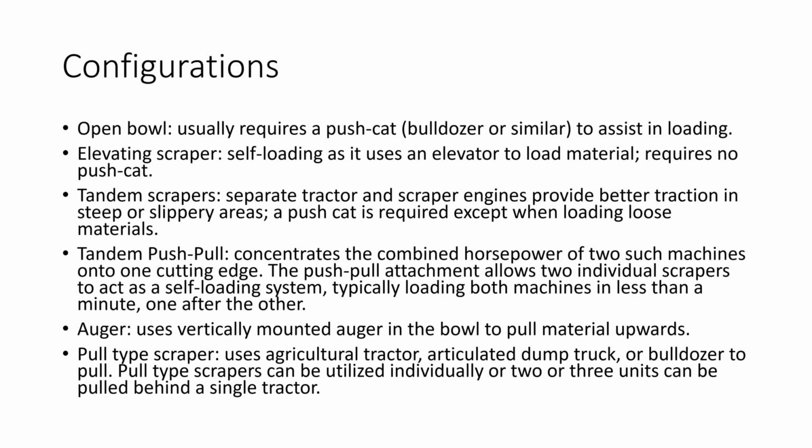A tandem loading scraper is a scraper that can act as a pusher for the vehicle ahead of it. And then once that vehicle is loaded, it will come in and be pushed by the next vehicle behind it in order to help it load. So the vehicle is now doing a fourth task. It's not driving across the road, it's not cutting, it's not spreading, it's also adding additional horsepower while empty and pushing a vehicle to fill it.